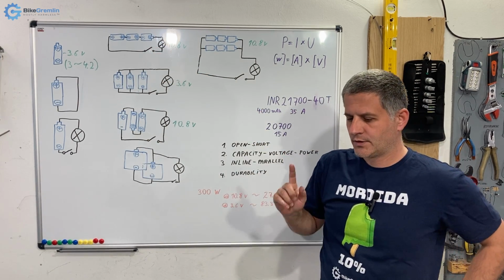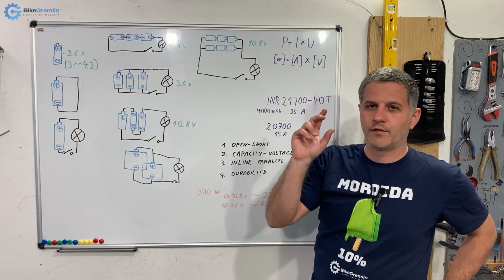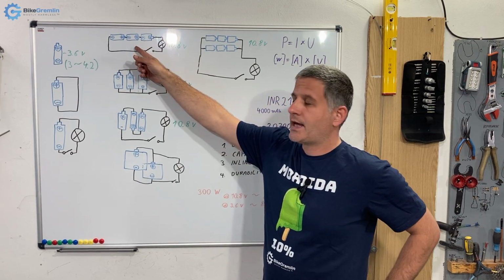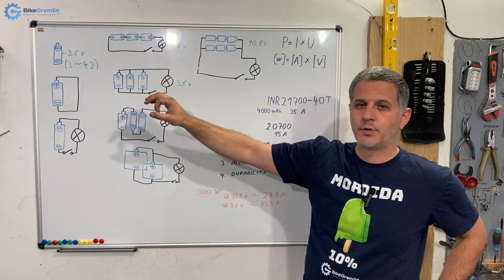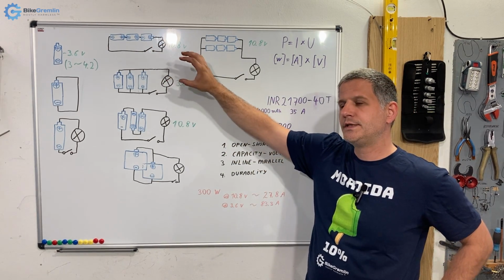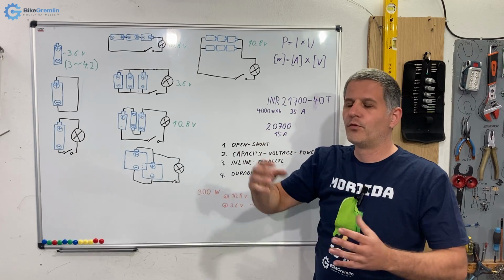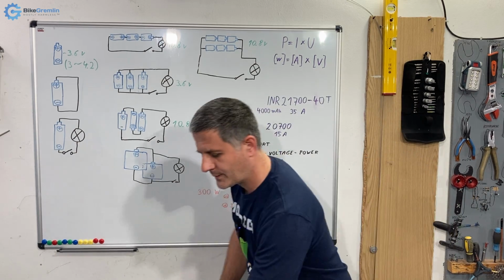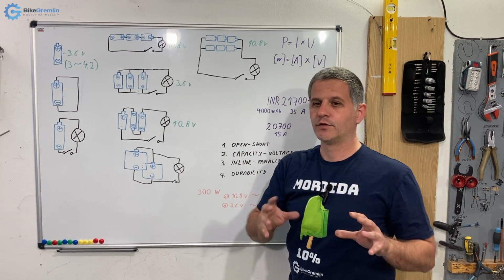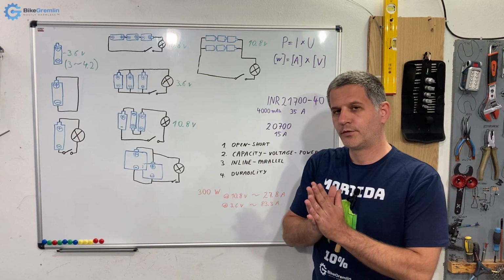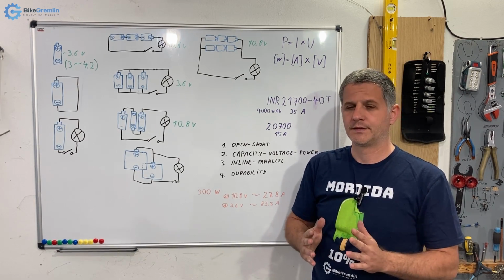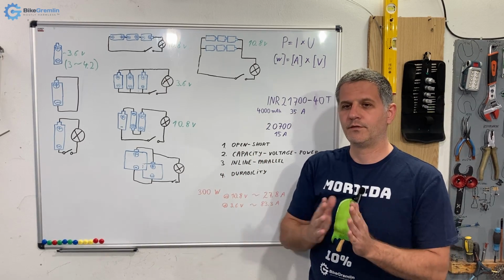However, it's not perfect. So when your phone says I have a 5% battery left, it could be that one of the cells is emptied to 0 and it's getting permanent damage, and the other cell is at 10% capacity. And what the tool measures in the end, the phone or laptop or your tool, when you wish to check on the voltage or capacity, it will give you a sort of an average. It's never ideal. So for that reason, it's not good to let your batteries discharge below 10%. It's better to recharge them when they reach 10%.